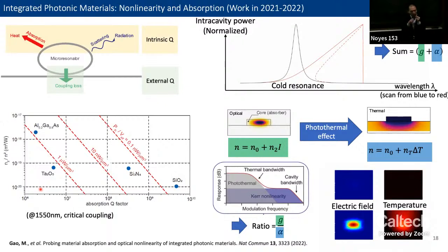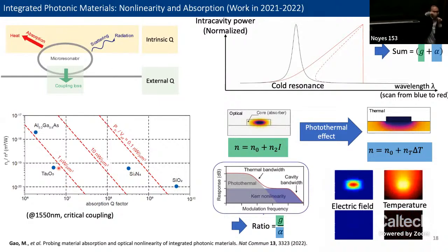Intuitively, the answer would be the band gap of a material. With a rule called Miller's rule, if you have a larger band gap, typically you will have a smaller nonlinearity. And with a larger band gap, because it's hard to transit the electrons between bands, typically you will have a lower loss. So the band gap is kind of the backhand physical principle that is governing this trade-off.